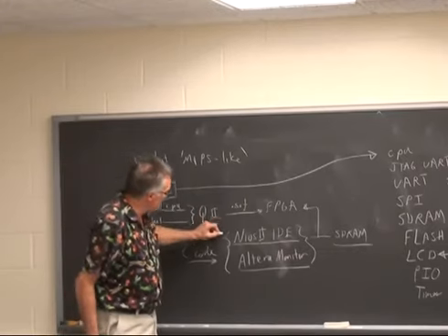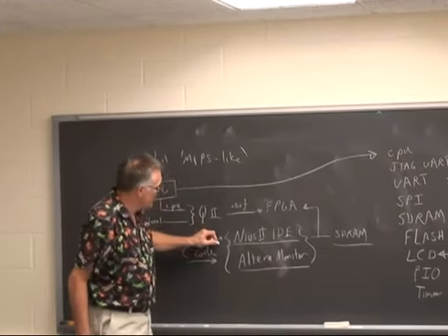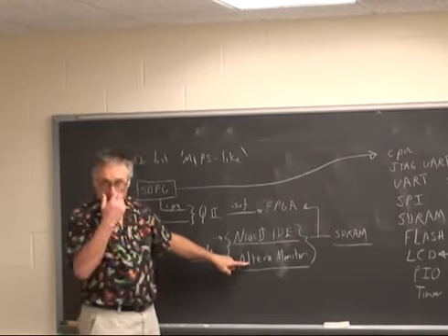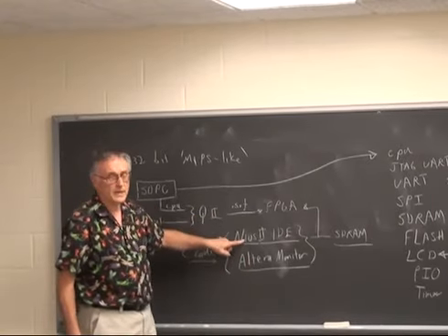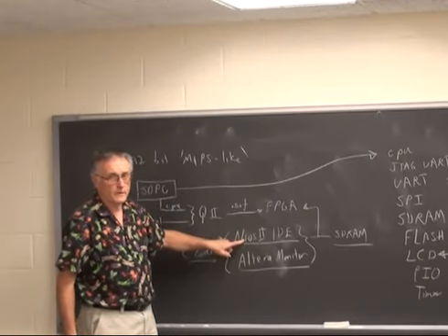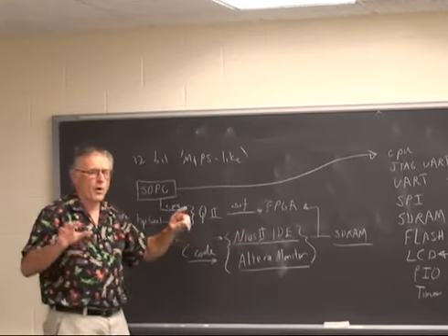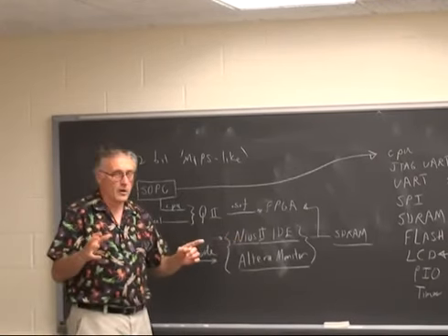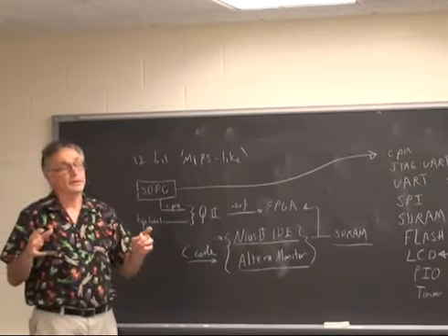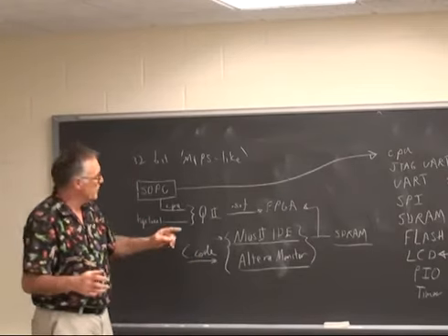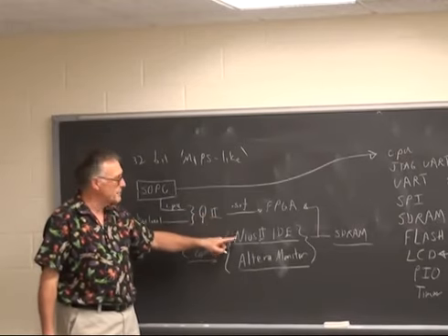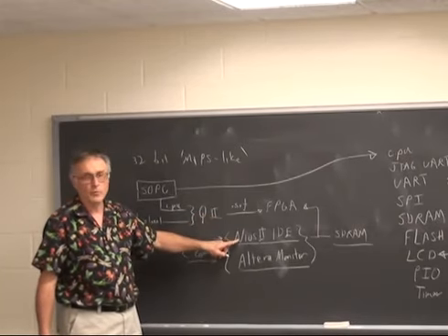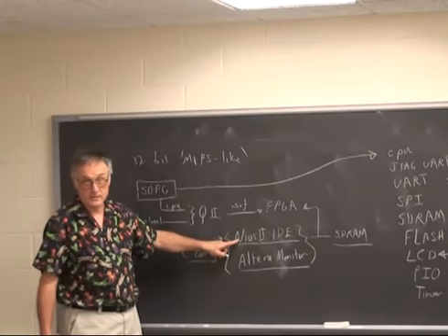The NIOS IDE is installed. The Altera monitor depends upon having Quartus 2 and the NIOS IDE both installed. All of these things are completely dependent on version. So version 10.1 of Quartus 2 will absolutely not work with 11.0 of the IDE, for instance.